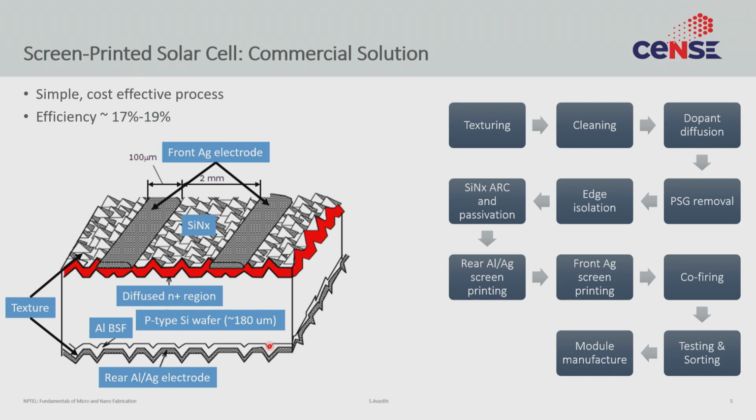So once again, we have a front electrode, where some part of the device is covered with metal. And the thickness of the metal top electrode in this case is around 100 micron, which, if you think of microfabrication, is huge. I mean, we are talking about nanofabrication at Intel. We have critical dimensions of 10 nanometers, but that is not the goal here. The goal here is to do what is barely enough, and 100 microns for silicon solar cells is plenty.